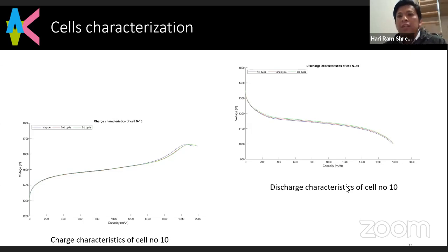In the Kitsune, we are using a lithium-ion battery, but in BIRDS-3 and BIRDS-4, we use a nickel metal hydride battery. A lithium-ion battery is more powerful, with high energy density and volumetric energy density. In the market we can get a nickel metal hydride battery with 1.2 volt nominal voltage, but in the lithium case the minimum is 3.7 volt. The size and weight are also important; if we put this battery in, it takes more space.